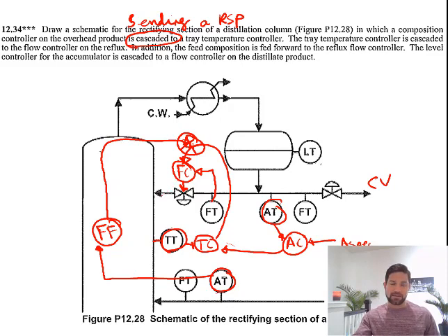One thing though that we may need to do is add a dynamic compensator. Depending on the time scale for which the change in composition affects the required change in the reflux flow rate, because again, changes are gradual, we could add a dynamic compensator either to the measurement value, or perhaps to the value of the flow controller. Likely, we could put the dynamic compensator on the sensor value, or perhaps it could be a filter value which acts the same way, adds a lag to the measurement.